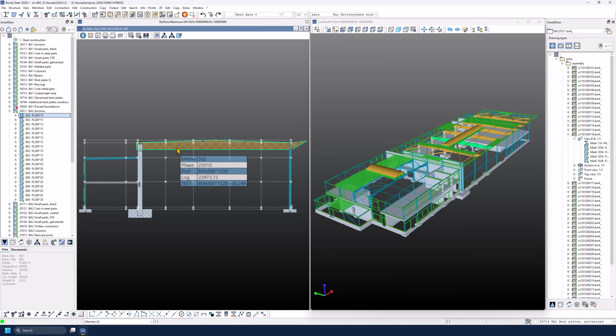And as soon as I hover over that component, I can now see a combination of profile plus material with a dash and 2 spaces in between. Like this, you could combine several pieces of information on a single line in this SmartInfo.